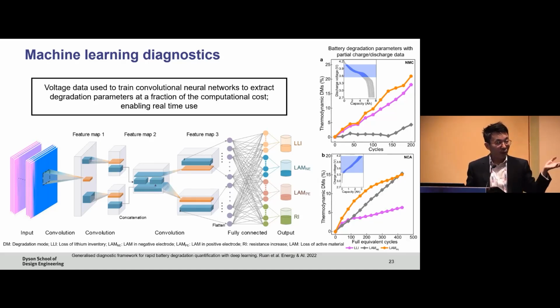If you think about degradation, if you're charging and discharging your battery at 2C and you get a certain level of degradation, a machine learning model might just fit linearly to that, and that's fine, but it might not capture the nonlinear roll-off in the battery. Physically, what's happening might be that you are cathode limited in one instance if you've got more anode in the system. And as you consume that excess anode, you transition to a different mode. Identifying the physical transitions, which this technique allows us to do, lets you understand and change the way you operate the system.